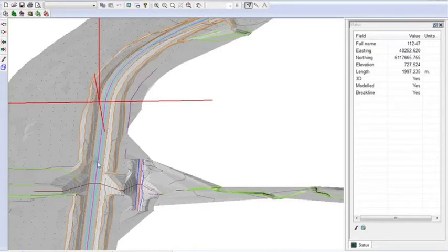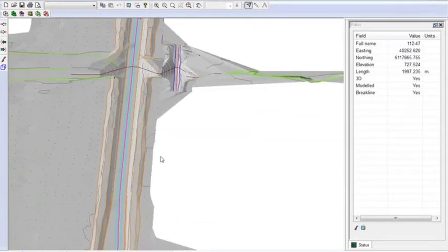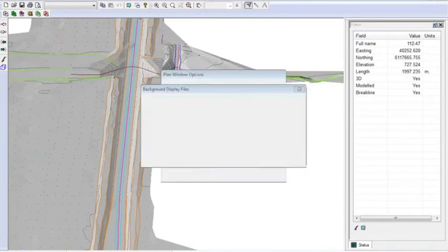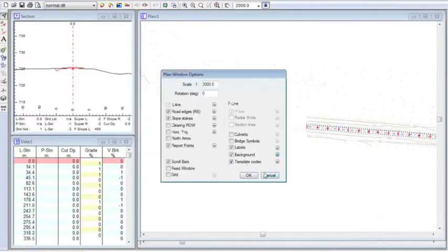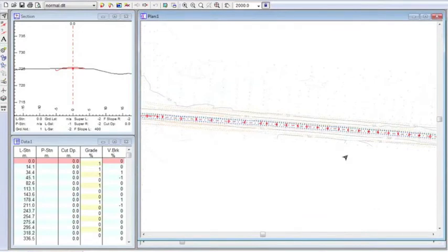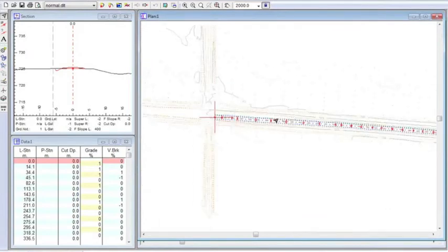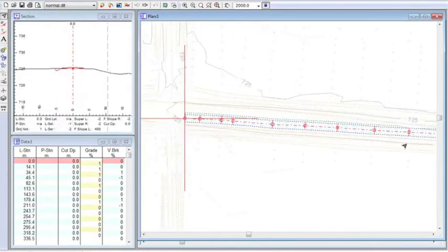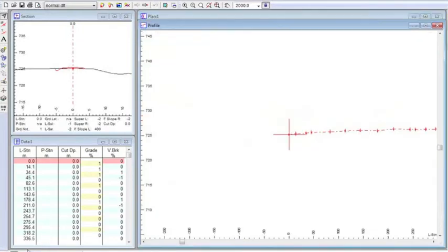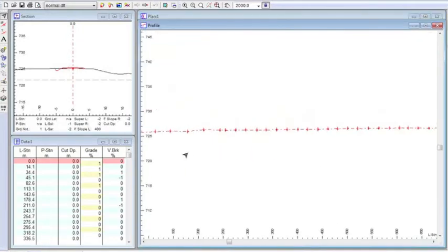And that curve is super elevated, and the survey picks it up and shows it. Okay, so I've got a nice terrain. Don't need to look at that anymore. And because I used that center line as my initial alignment, my road already exists. It's already got a bunch of IPs that represent the surveyed points. It's even got a vertical alignment that represents the surveyed points, and it's following right along the ground. The ground in this case being the center line of the road.